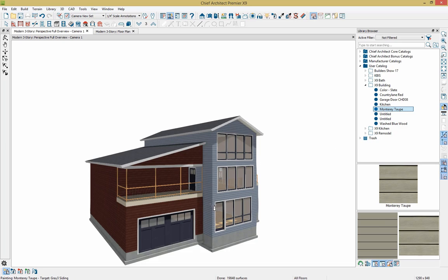So instead of clicking on each individual wall, down in the bottom here, we do have additional options on how you're going to apply that material. So I was in component mode for each individual wall. You can do room mode. So if you wanted to change all of the different cabinets in one room, you can do room mode, floor mode, or plan mode. I'm going to get into plan mode since this goes across multiple floors and so forth. So that really changes the scope of how your material is applied.